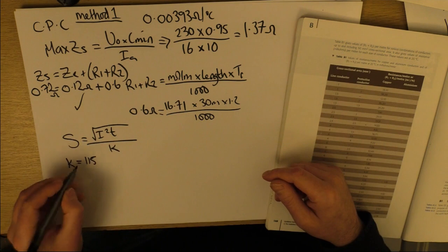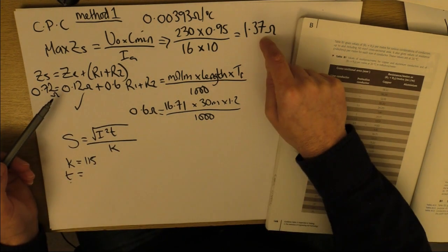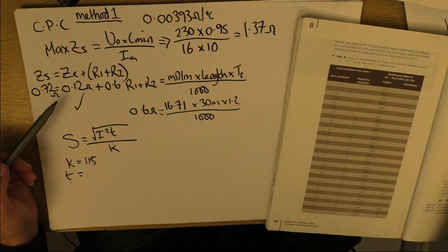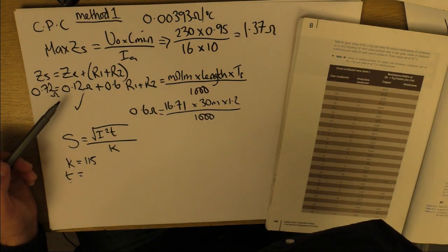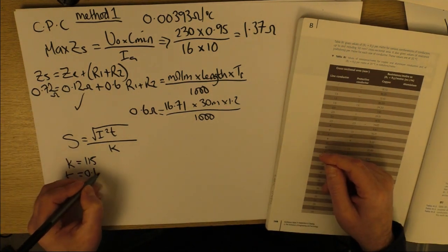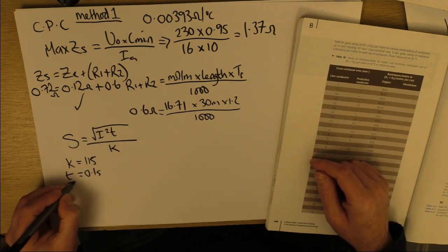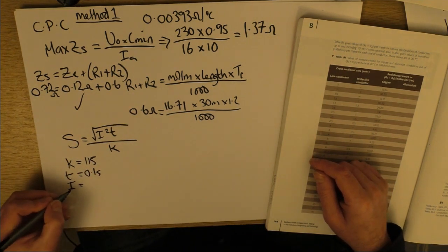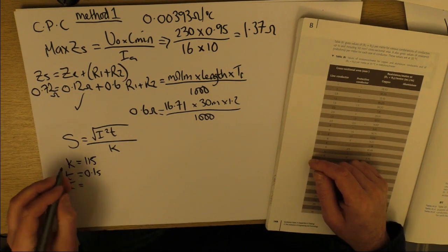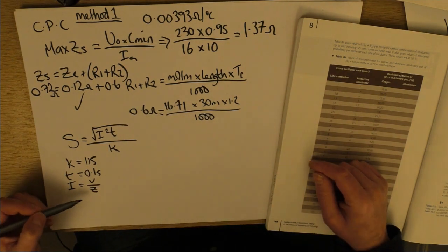Now, T. Because we know we're under the max ZS, we know that it's going to trip almost instantaneously. Appendix 3 in the regs, time current charts, I'll tell you that. But our T is 0.1. Now this is the fault current that's going to occur due to our ZS. Now it's just Ohm's law again.